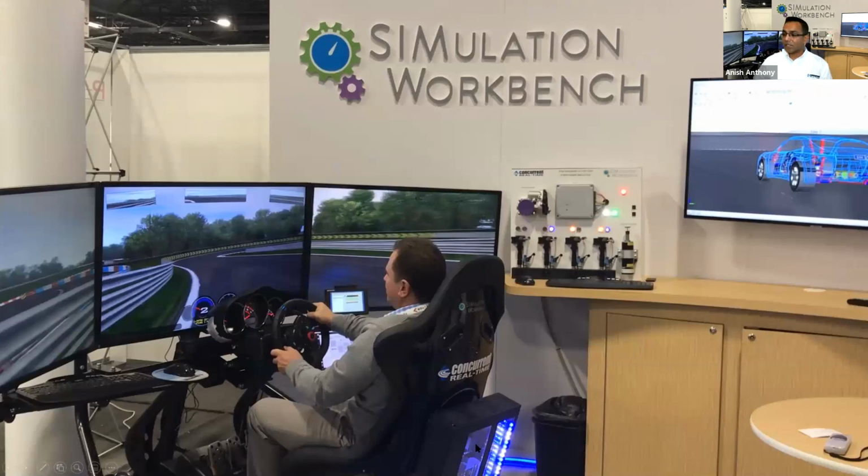Below the car seat, you will see the real-time computer, which is simulating a high fidelity, 400 degrees of freedom vehicle dynamics model, along with a complex Simulink control system model. There is real hardware, the steering wheel, brake pedals, and also the ECU, which is the car computer. And this is all connected.